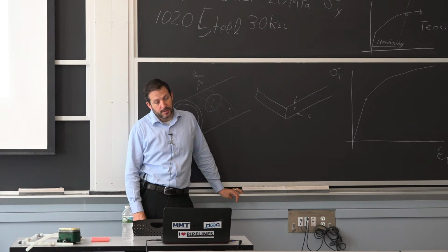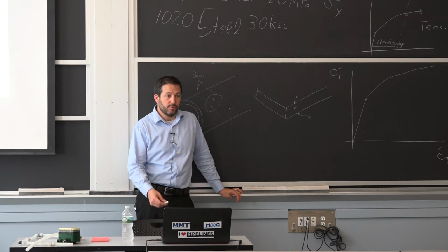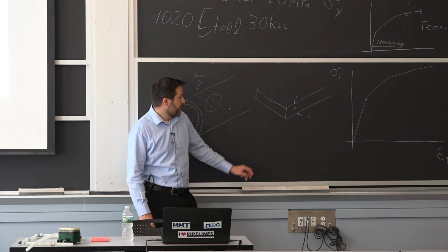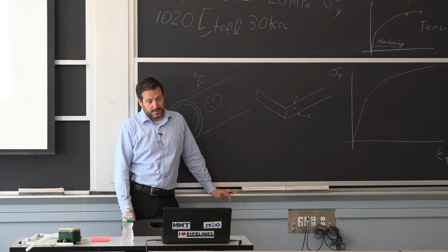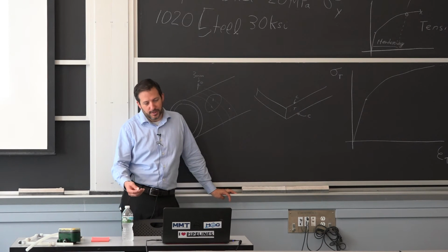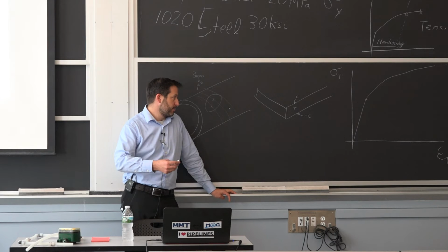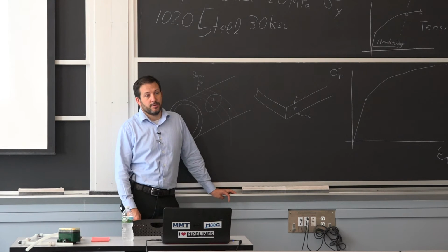So a lot of times, if you want precision and less trouble when you machine, you have to use a grade that doesn't have a lot of this residual strain in it. It's not easy, because if you go for an aluminum alloy that has a high strain, a lot of times it has gone through a heat treatment, and that's why you are getting some distortion when you machine it.